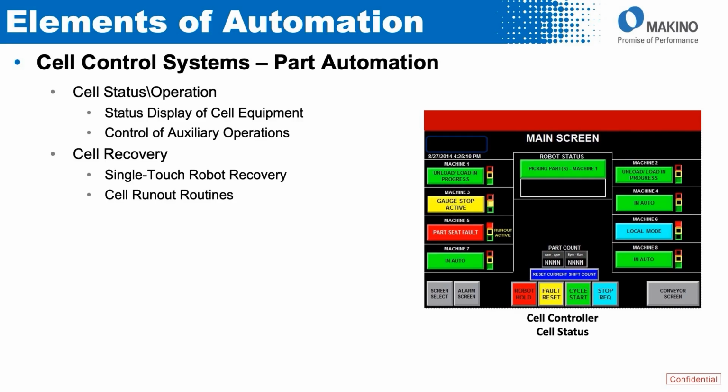It'll bring the robot back to a home spot, and you're able to reset the cell. You want to keep that teach pendant out of your operator's or maintenance guy's hands, so you don't have to call a maintenance guy to recover it. So try and keep that teach pendant locked away in a box so you don't have to use it.